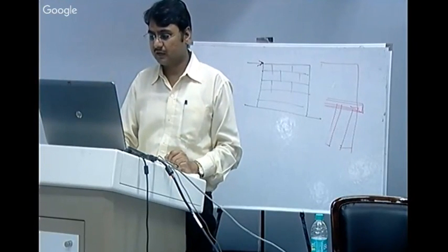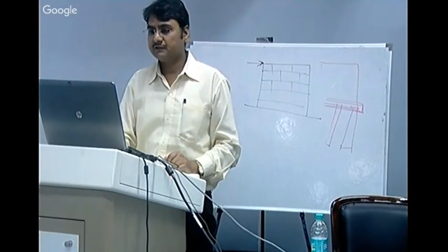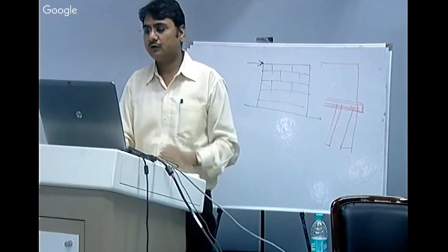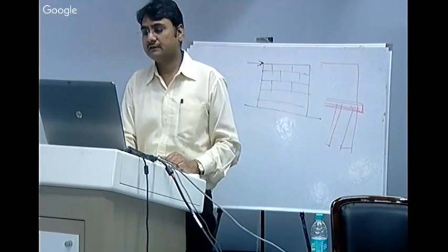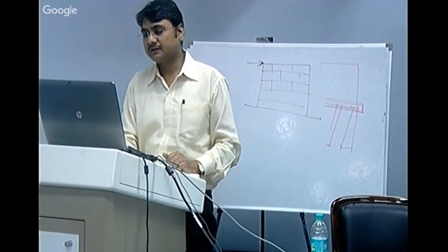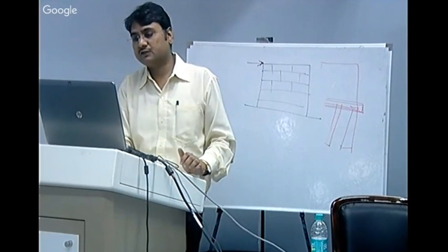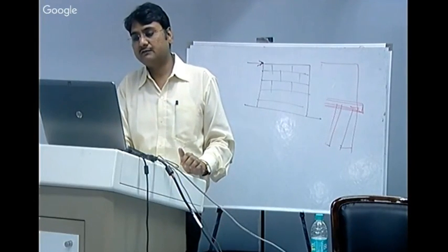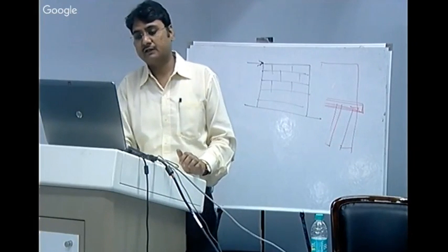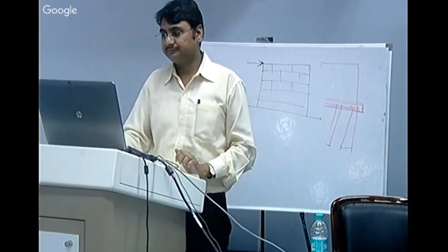So these are some of the pictures of the pattern of how these corners fail. Here you can see the out of plane failure, and the corner has failed because of that. This is also separation of unconnected adjacent walls. This room and this room, you cannot see. Here are two rooms, and one wall of one room is not connected with the other one. So that's why it failed.